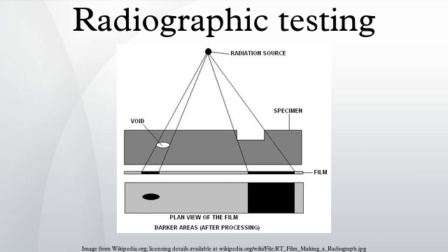Defects such as delaminations and planar cracks are difficult to detect using radiography, particularly to the untrained eye. Without overlooking the negatives of radiographic inspection, radiography does hold many significant benefits over ultrasonics, particularly insomuch that as a picture is produced, more accurate identification of the defect can be made, and by more interpreters.